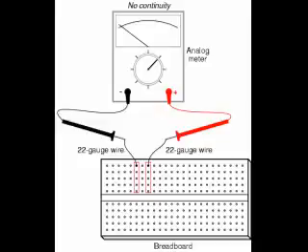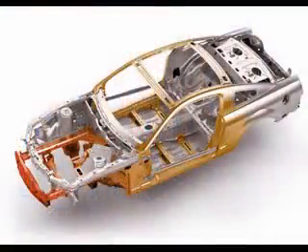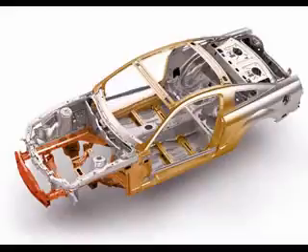Many electrical and electronic systems use common connections. Almost all cars use a negative ground connection that is connected to the metal chassis. This effectively uses the car frame itself as the conductor to the negative side of the battery. The negative side of the car battery is connected to the car chassis.